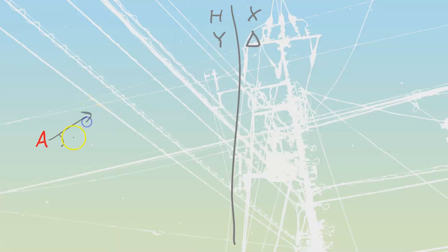One is going to be off at 30 degrees, and that is going to be from A to neutral, the very first line that we draw, whether physically or mentally. And the second one is going to be off at 60 degrees, and it is going to go from A over to wherever I'm going to place my phase B. Draw these two in. Once you've got them drawn in, then we are going to start doing the actual diagram. So the first thing that we're going to do now that we've got the basis of the diagram, A neutral and A to B, is we can drop in phase C. We know where that thing's roughly going to end up.